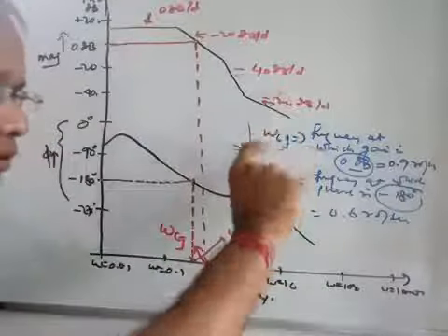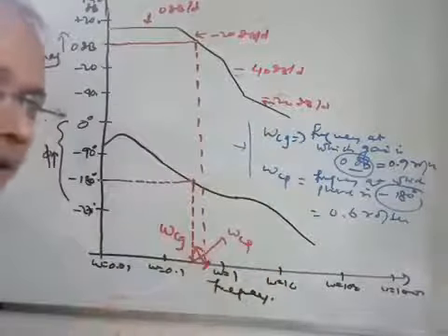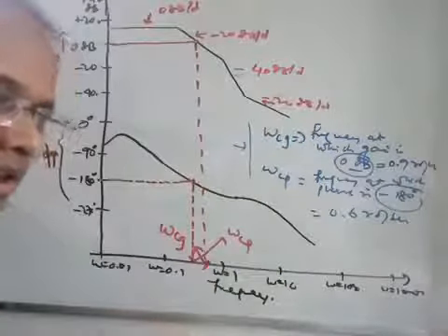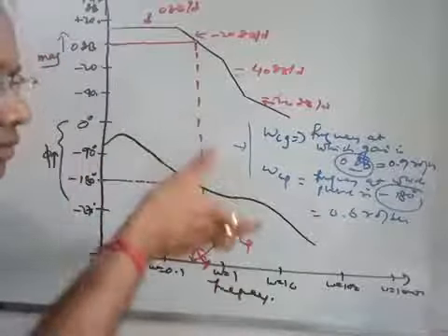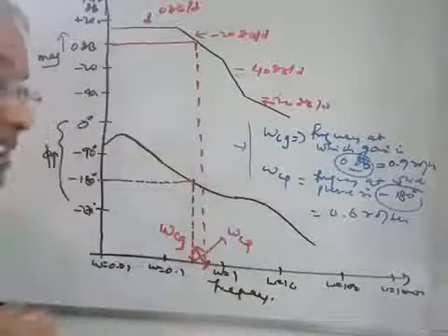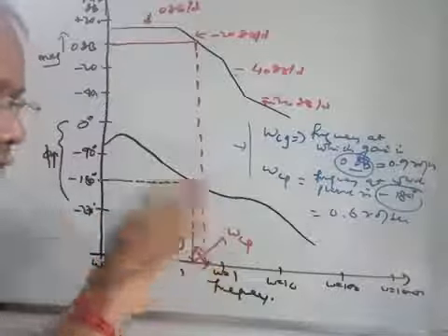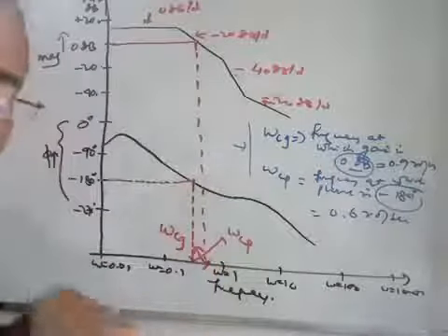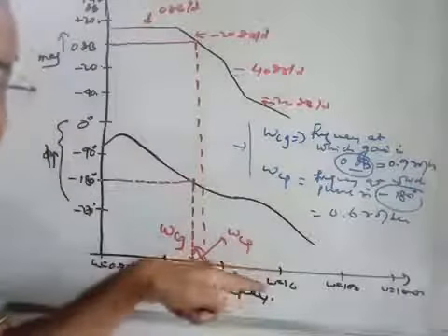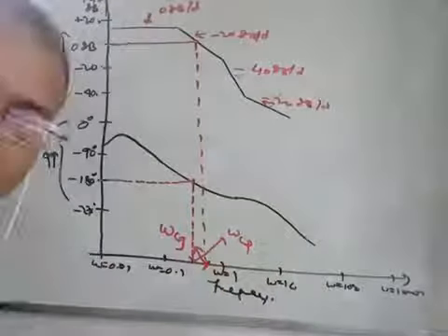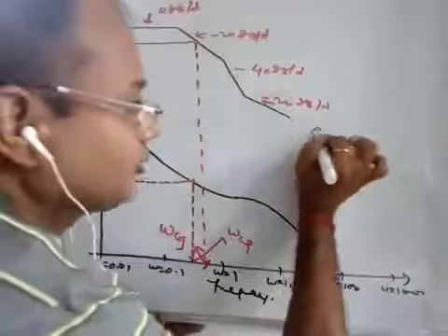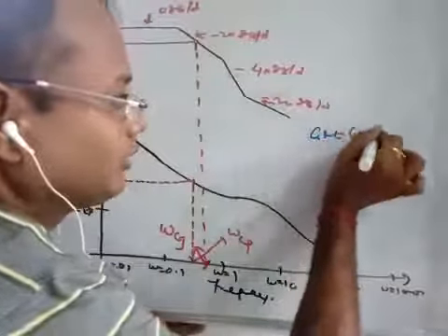Once you get these two frequencies, you can also address the issue related to stability, but we have to find all four parameters. Next, we have identified these two parameters. Now gain margin and phase margin are related to these frequencies, right? Next is gain margin.